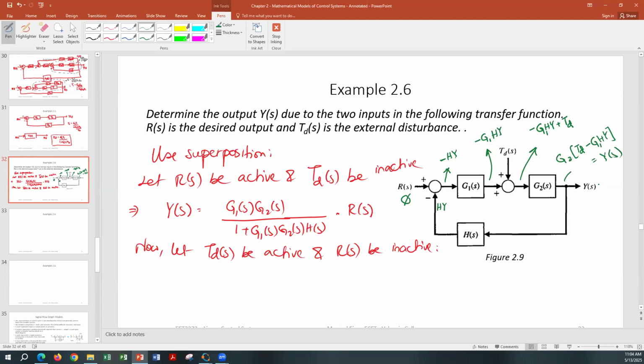If you want to make it in phase, then you put an inverting amplifier at the output of a summing amplifier to make the input and output phase the same usually. But in that case, as I said, just consider that in the summing amplifier two signals are coming in, one signal is 0, the other coming in is a negative signal. So the output is just going to be a negative value because that's being subtracted from the input. So whatever you want to assume it to be.